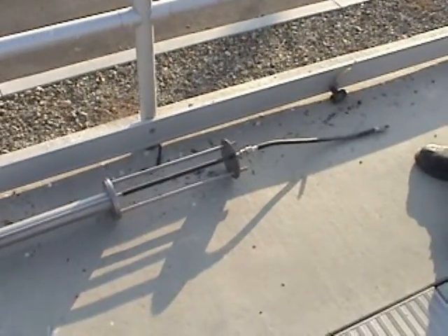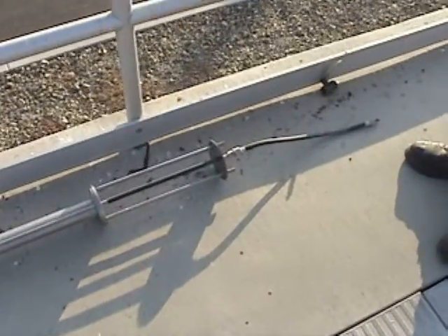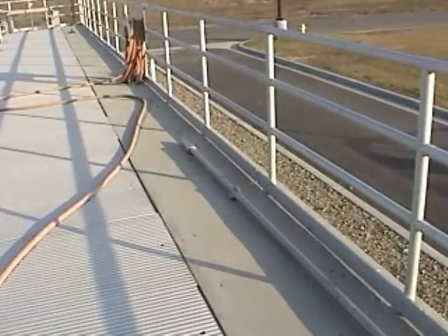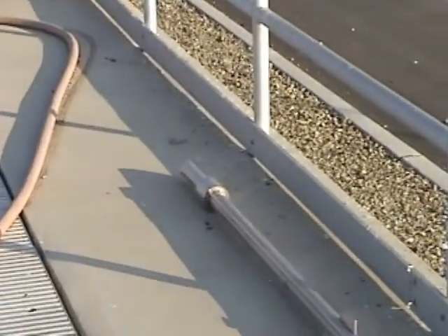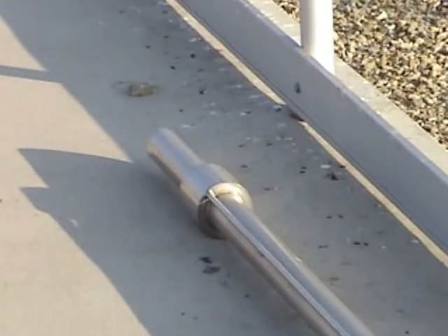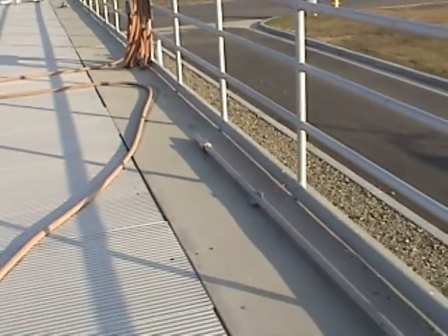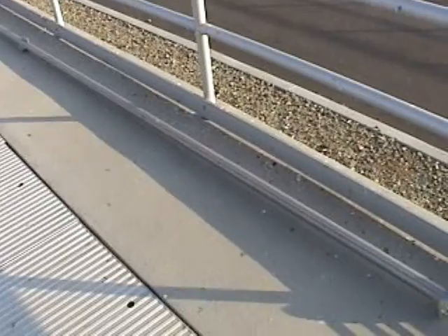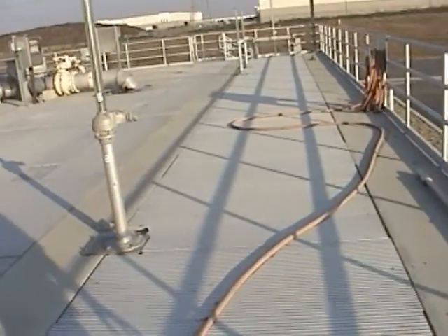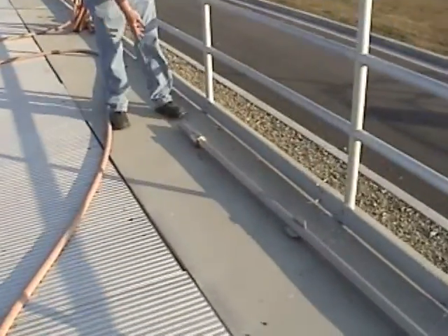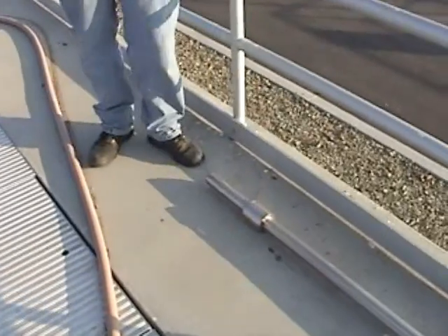I think the big thing to watch for, if you come by, is that sometimes sand will become impacted in the end of that tube. If you raise it up like I did to show you that filter and shake it a little bit, see if you can loosen the sand up. That's one thing you can do, or you can pull the whole tube out like we did right here and take a look at that. The biggest problem I've seen is if you have plastic debris covering the end of this tube. If this gets plugged up, it'll cause the filter to fail.